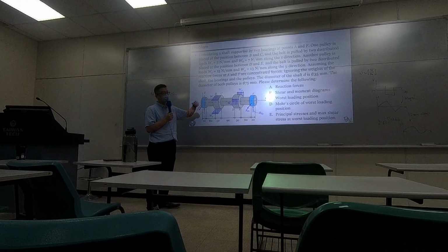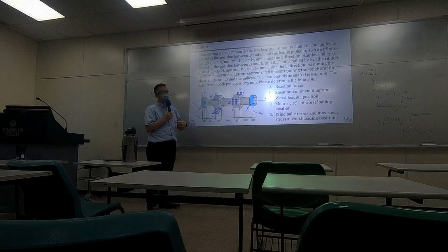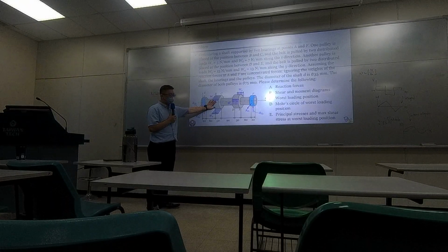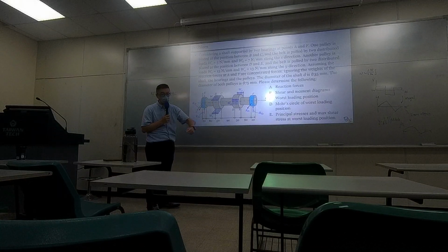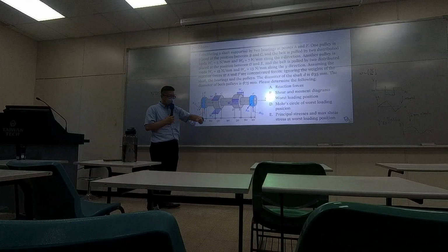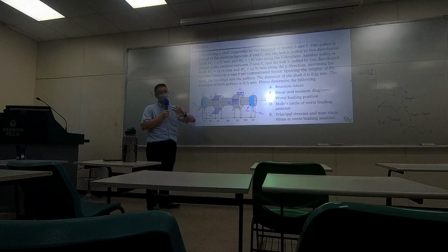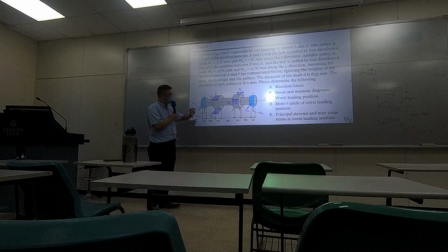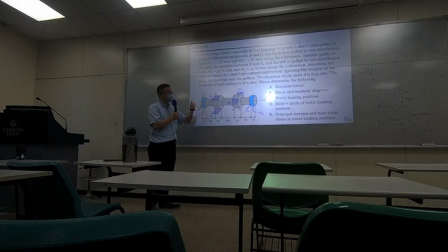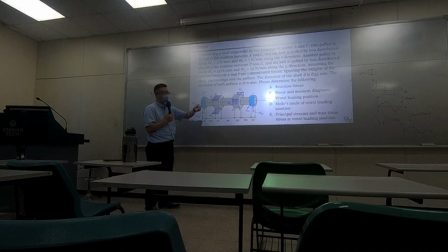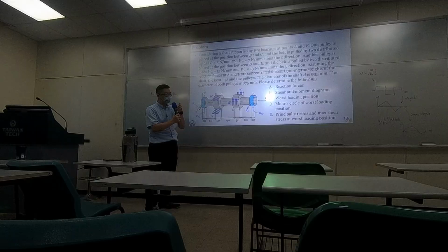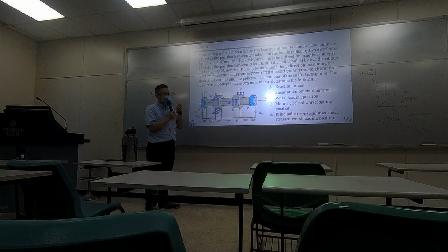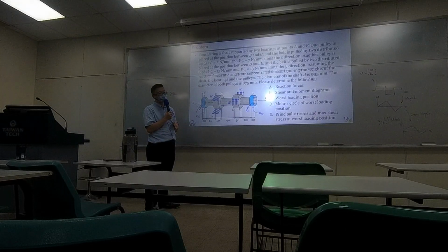That's how the belt can generate a difference of torque, and the difference of torque allows this rotational geometry to rotate. This cylindrical object rotates. So that's why you can drive the shaft by a difference of tension forces on both sides of the belt.